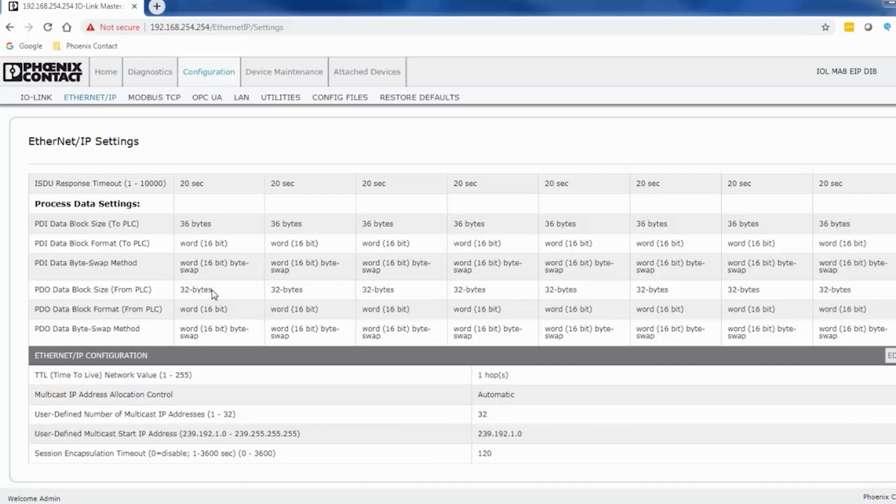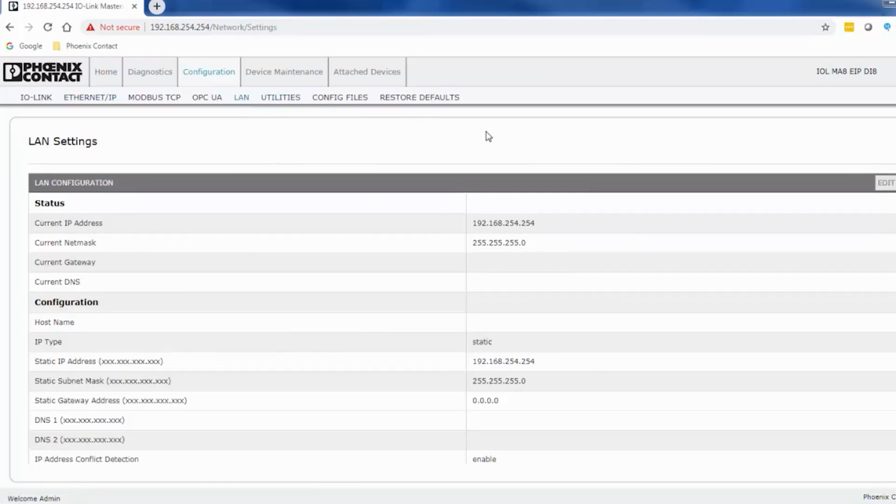The data can, but does not have to be, modified to more closely match the amount of data your IOLink sensor supplies in its process data channel. But note, if you change the channel sizes, you're also adjusting the module's total produced and consumed size to the Ethernet IP master. For example, and for simplification, we're leaving all the settings at default.